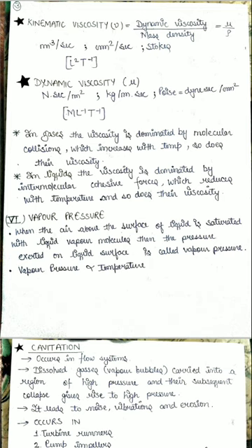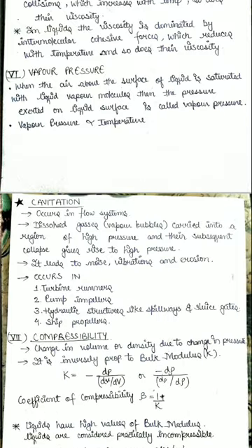In gases, the viscosity is dominated by molecular collisions, which increase with temperature, and so does their viscosity. In liquids, the viscosity is dominated by intermolecular cohesive forces, which reduce with temperature, and so does their viscosity.